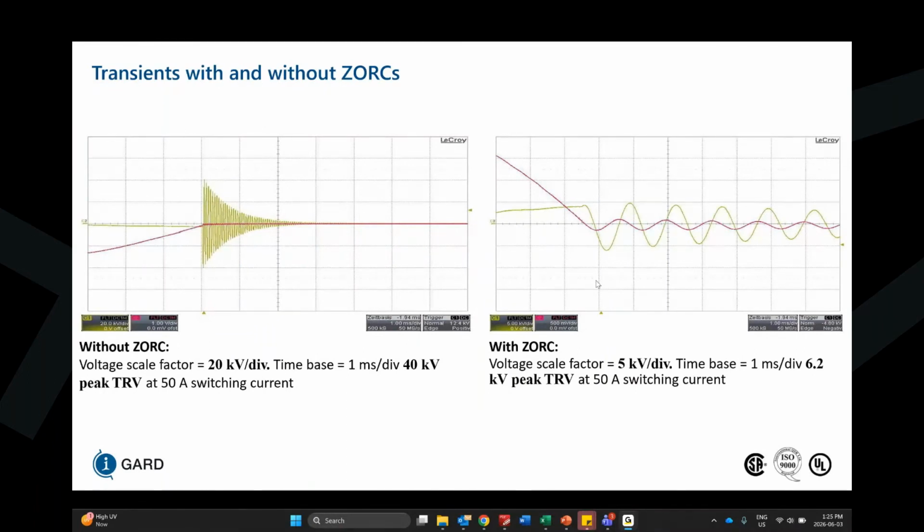Can you please explain what RC only means in the table you showed earlier? For RC, it just involves the capacitor and the resistor. And that's the standard surge suppressors that were used in the past. But now a lot of modern surge suppressor units include a zinc oxide portion, which is basically a variable resistor that is intended to handle even higher frequency transients better than the standard RC snubbers that are on the market.